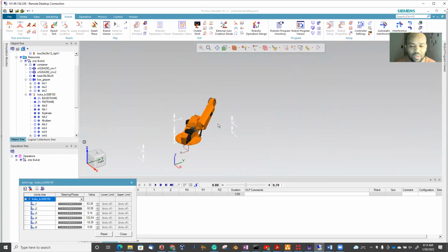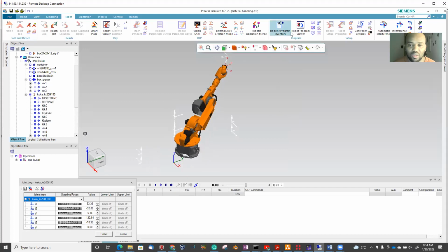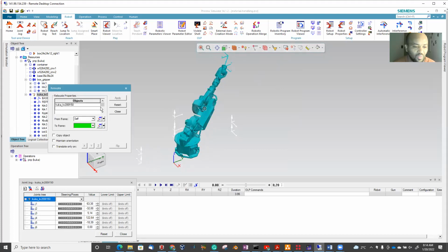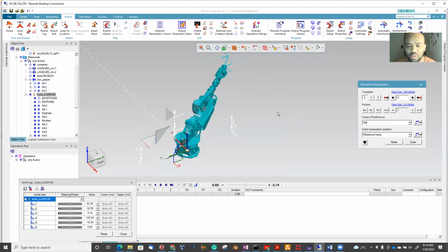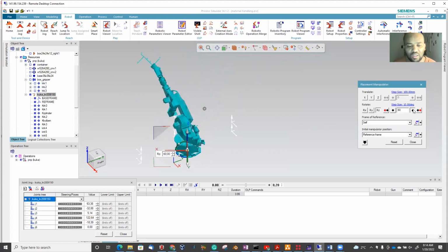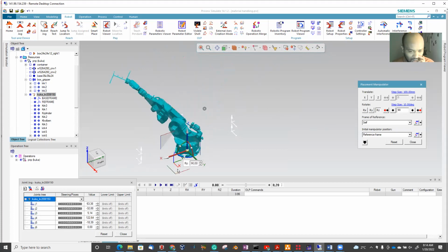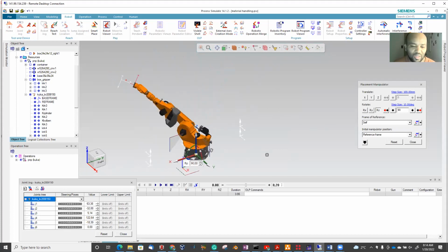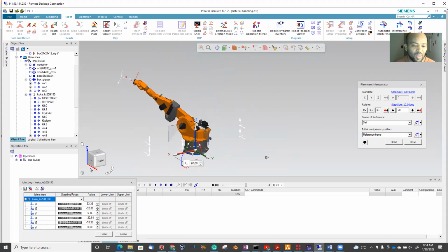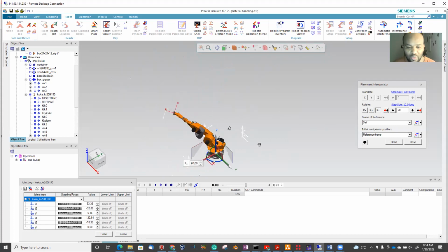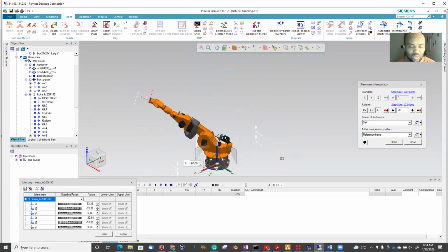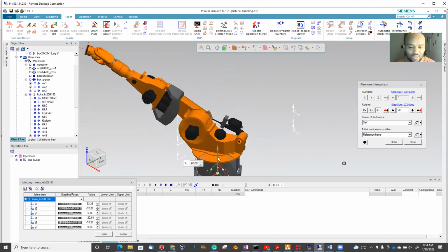But the global doesn't matter because I could change the orientation of the robot anytime, I could relocate the robot, for example rotate it about the z axis, and then it is different from the origin. So it doesn't help us to relate to this global axis. The rotation about the z axis is along this.